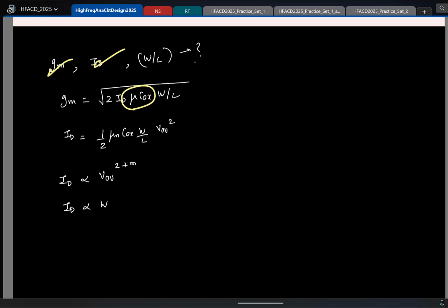So let's see what we do. As a designer, what parameters of transistors are you interested in? If you are designing an amplifier, let us say, what parameters will you be interested in? GM. What else? Yeah, W by L. And let's start with small signal. What are the small signal parameters you will be interested in? Yeah, the gain, that's basically GM, or I will say GDS.